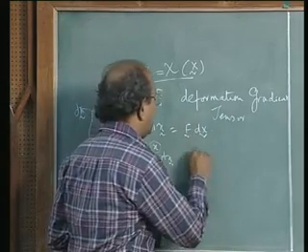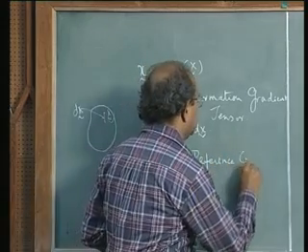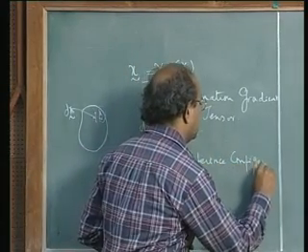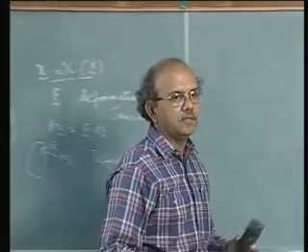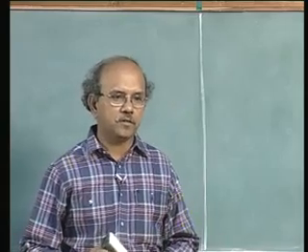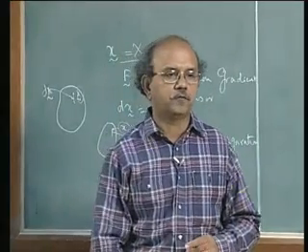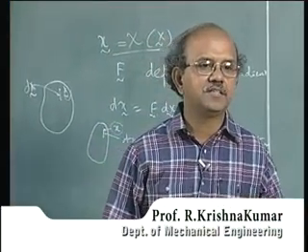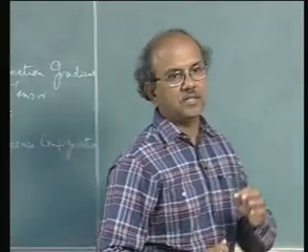We have not defined the reference configuration. The reference configuration is extremely important in the study of mechanics. There are various definitions for this. One very important aspect of the reference configuration is whether it is a stress-free configuration. Most of the cases we treat a stress-free configuration as the reference configuration.